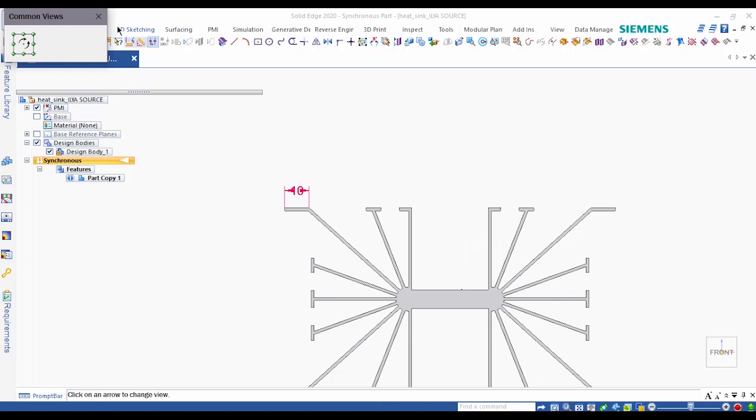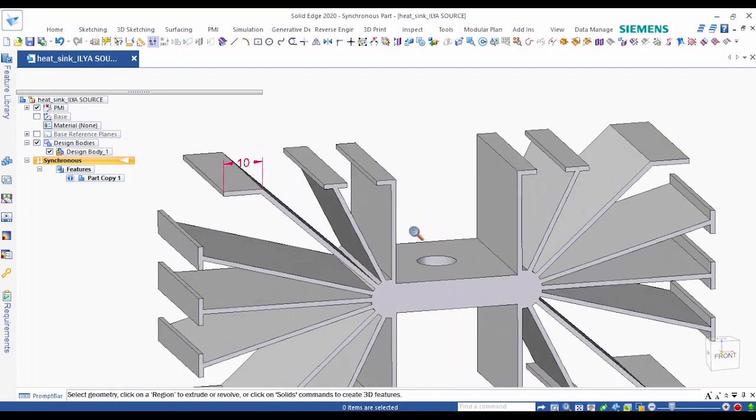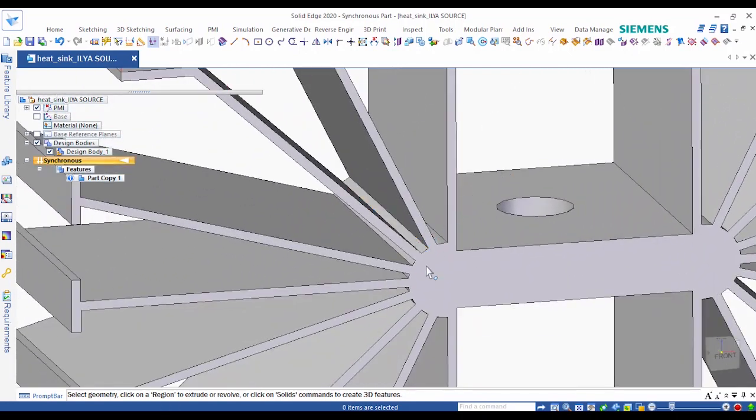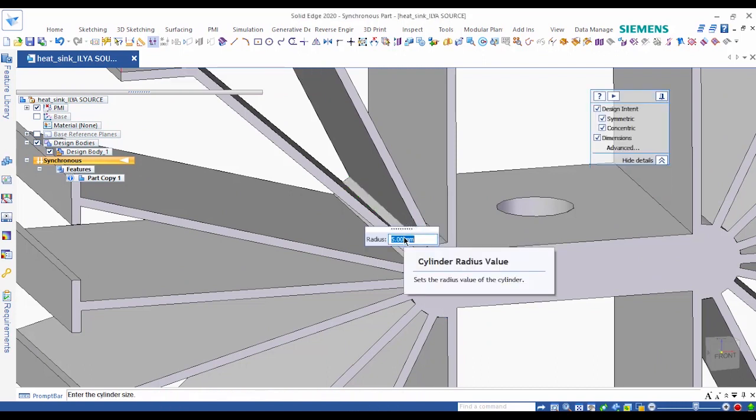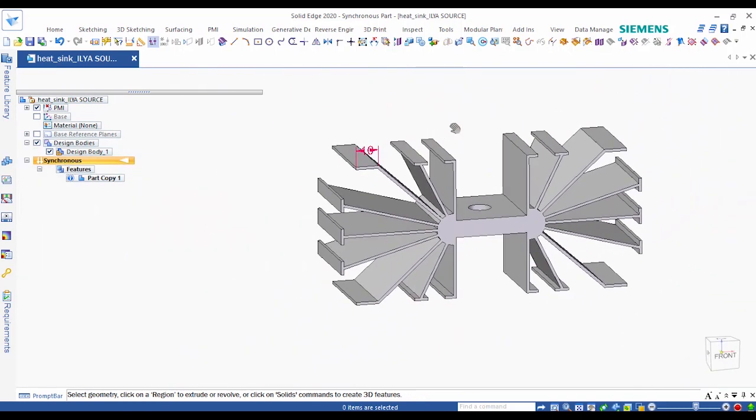But look at all the little sections between the fins. I guess I'll have to draw a few circles. Wait, let's use Solid Edge and just make the change like the list says. Watch, I'll touch the radius section and Solid Edge will tell me what size it is. See, it's giving me the chance to change to a new dimension. So let's go from 5 millimeter to 7 millimeter. Oh, that's too cool. All the sections changed. Yeah, and they changed on both sides of the model.